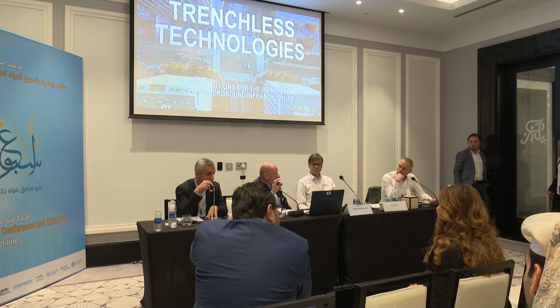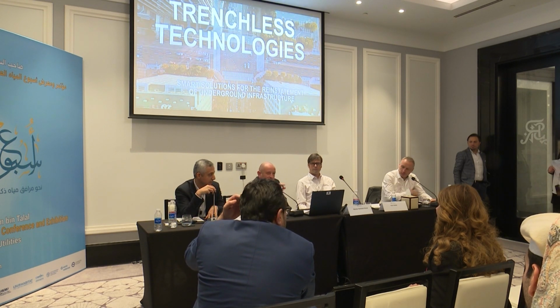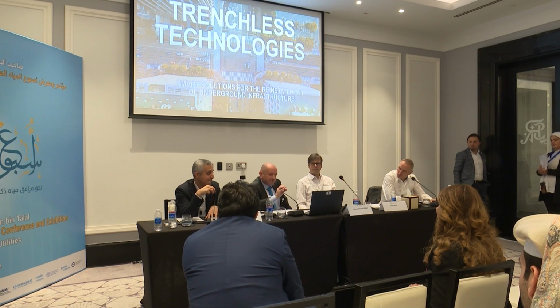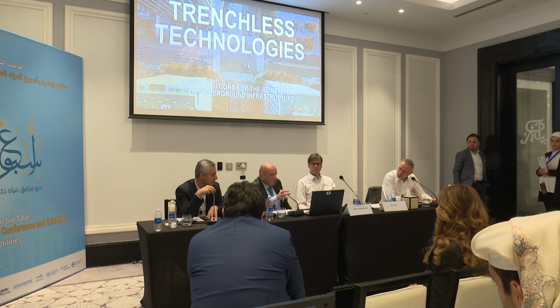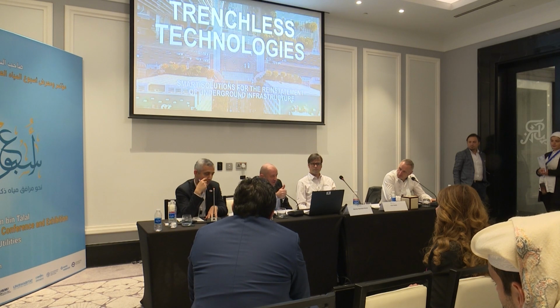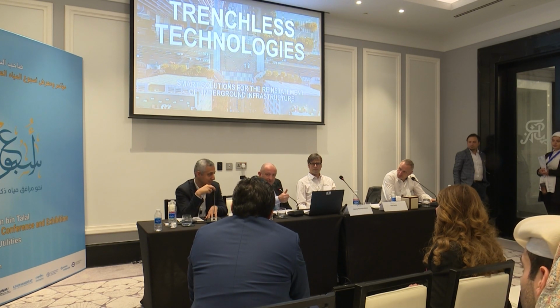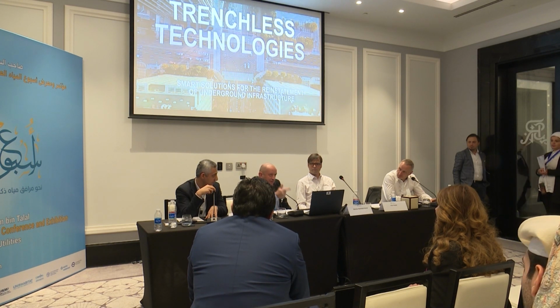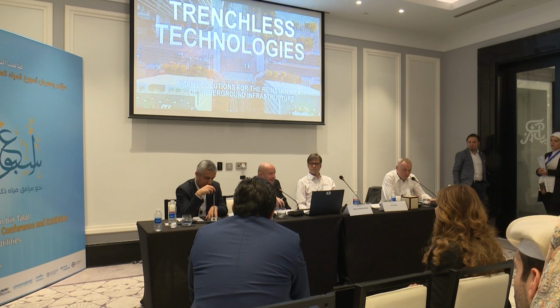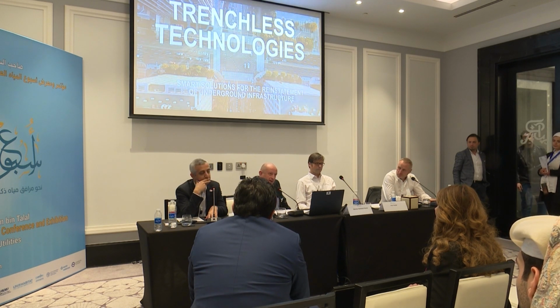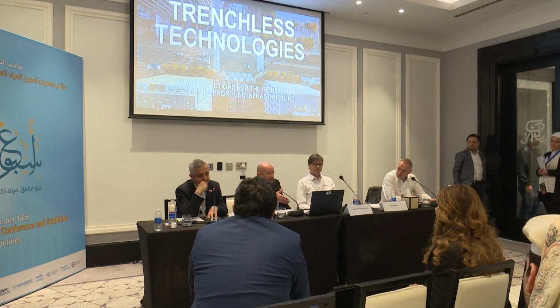For a simple case, take 100 years as an average life cycle of a pipe. That means a city with 1,000 kilometers needs to do 1% every year, which is 10 kilometers of rehabilitation. So if you decide it's more, you decide it's more. But the practice shows, if you wait too long, the future generation can no more handle it. That is what he said to me: we shift our problem onto the future generation, and they can no more handle it.